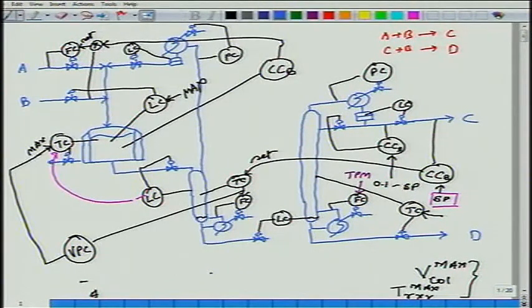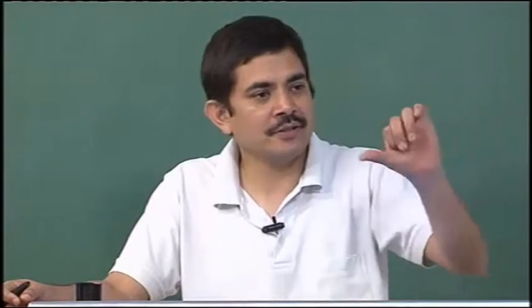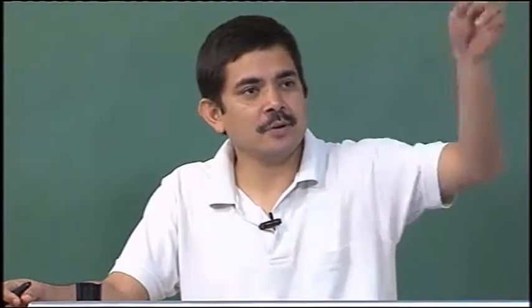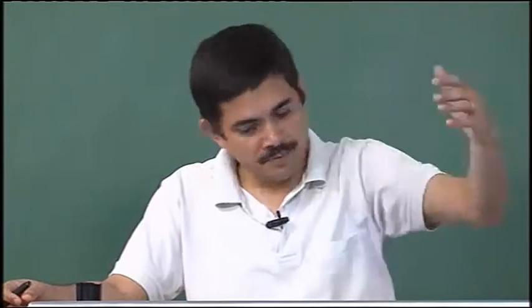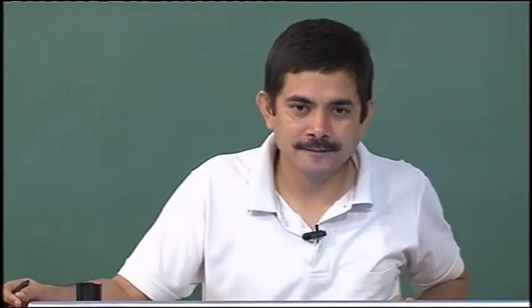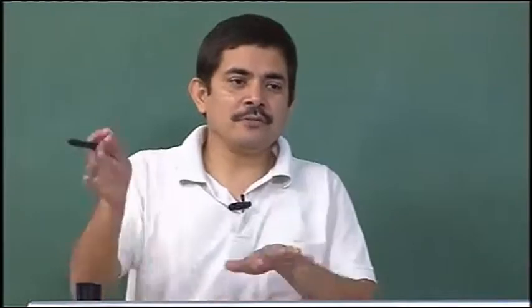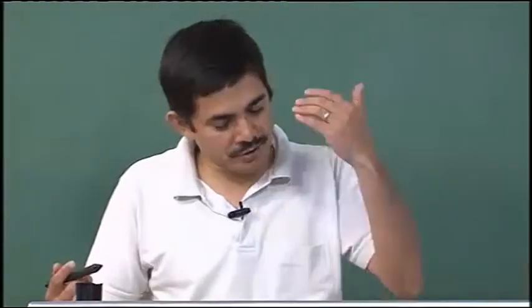You can take this logic further and then say that, look, what is my processing rate? The feed to the process is not in my hands, it is set by some upstream process. You see what I am saying? Upstream process is saying that, look, this much fresh air is to be processed. In that case, my throughput manipulator is not in my hands, it is what? It is the fresh air feed stream. Its set point is coming from some place, and whatever is coming needs to be processed. Nevertheless, the operating philosophy, optimal operating process philosophy for this process will remain the same.